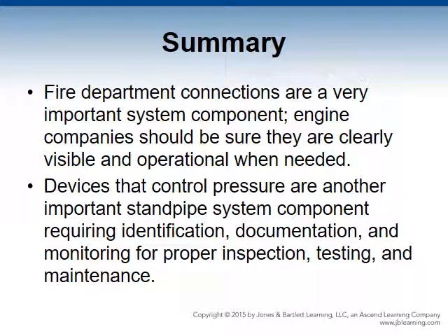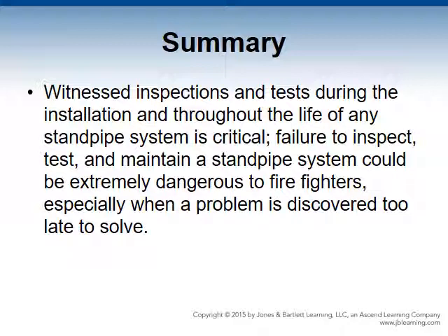Fire department connections are a very important system component. Engine companies should be sure they are clearly visible and operational when needed. Devices that control pressure are another important standpipe system component, requiring identification, documentation, and monitoring for proper inspection, testing, and maintenance. Finally, witness inspections and testing during the installation and throughout the life of any standpipe system is critical. Failure to inspect, test, and maintain a standpipe system could be extremely dangerous to firefighters, especially when a problem is discovered too late to solve.